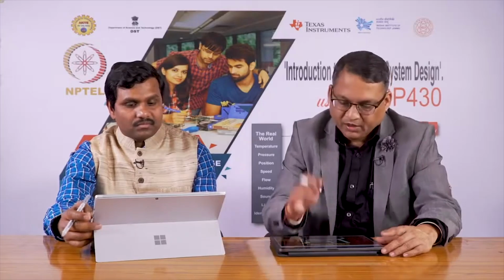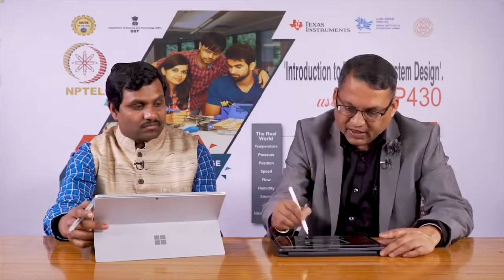Even oxidized copper would not allow a good PCB to be made, and therefore, it is strongly recommended that you first prepare this surface of the raw PCB, and for that the best method is to use a sandpaper. Before that, let me also mention that the PCB itself is of various types.